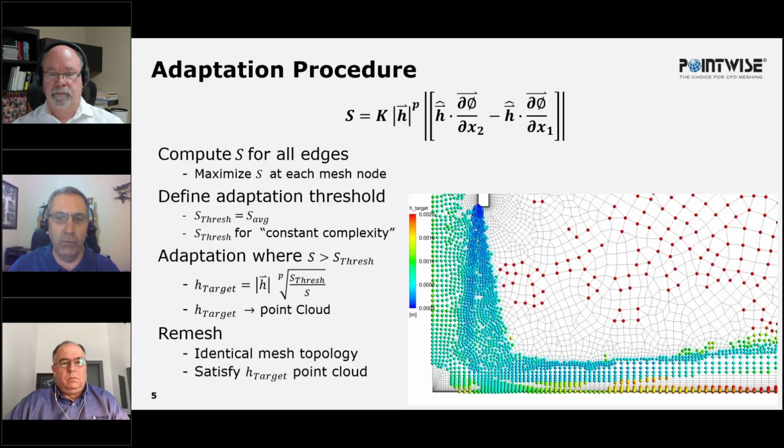If you selected that, you would work on the worst discretization error in the problem, and you would bring the discretization error down if you simply selected the average every time. However, that can be wasteful and also can not really allow you to assess how far along you are with respect to convergence of the entire solution.